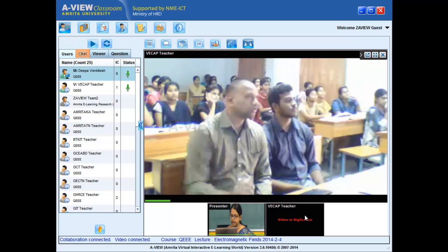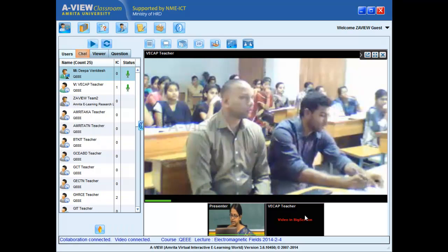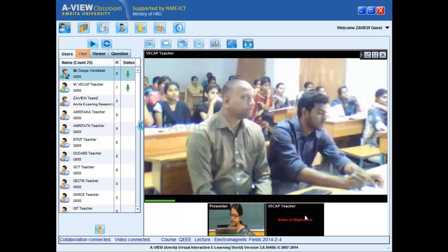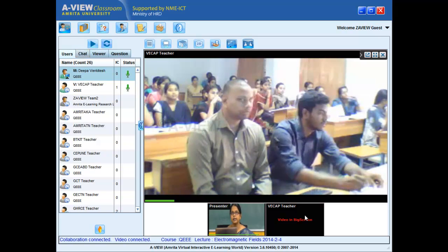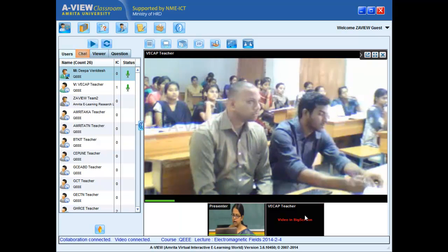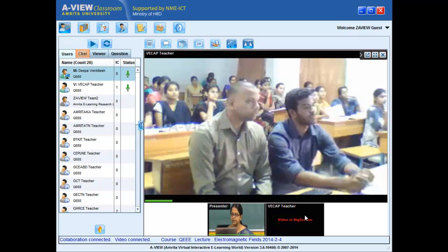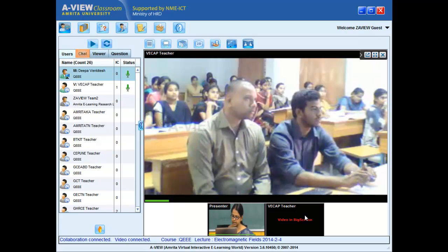For example, I could have the resistor here, inductor here, and the capacitor and conductance here, or I could have the resistance and inductance in series this way and then the capacitance. All this is actually a model for an infinitesimal length delta Z of the line. So the RLGC that we are talking about are the R's, L's, G's and C's of the line per unit length.